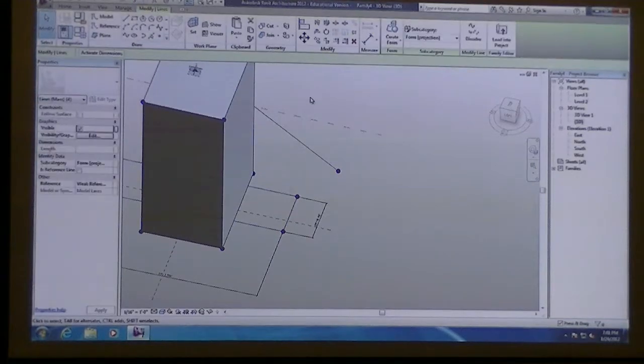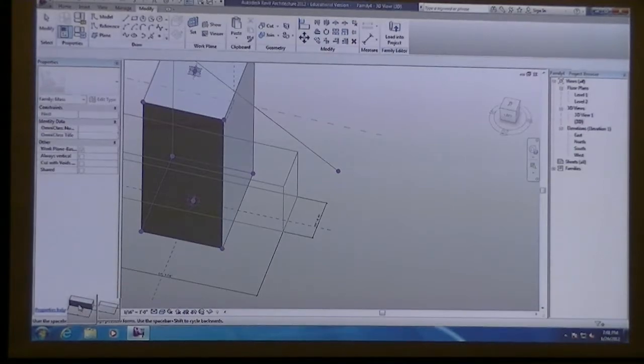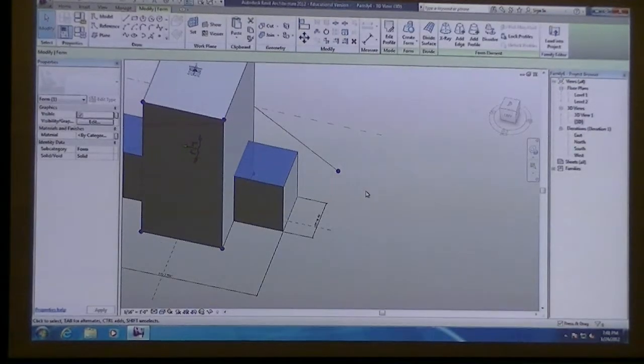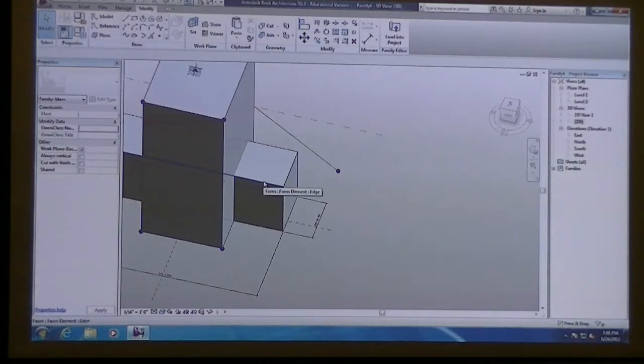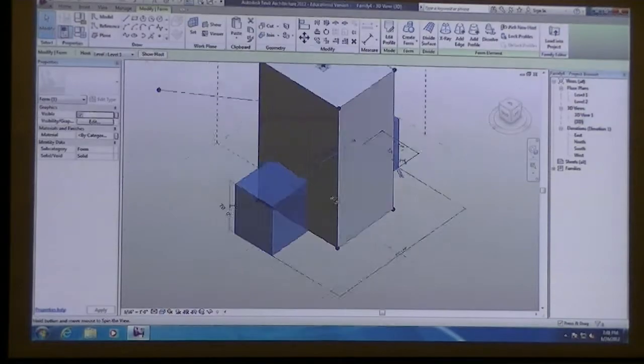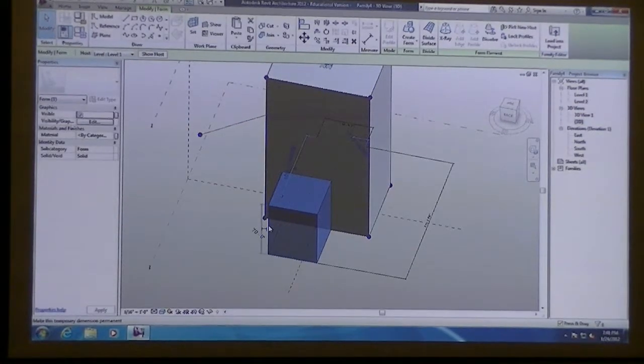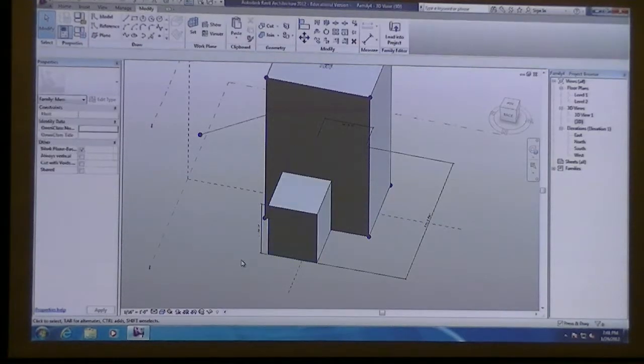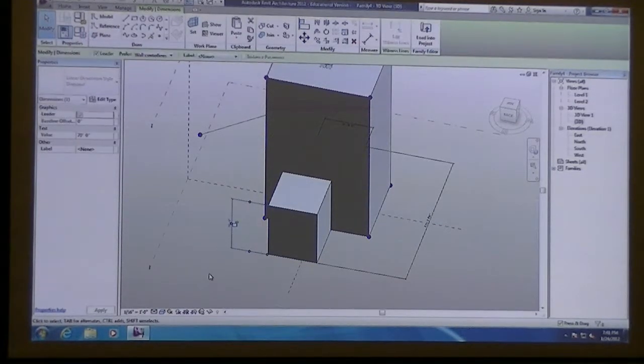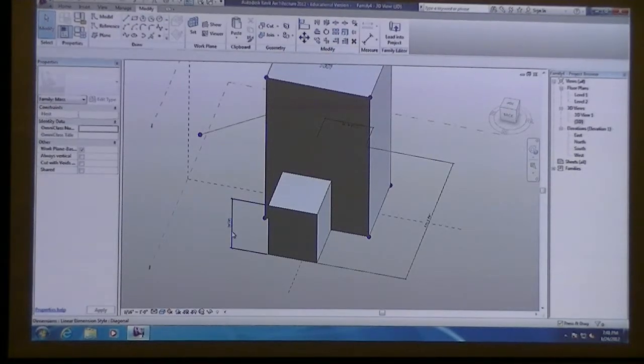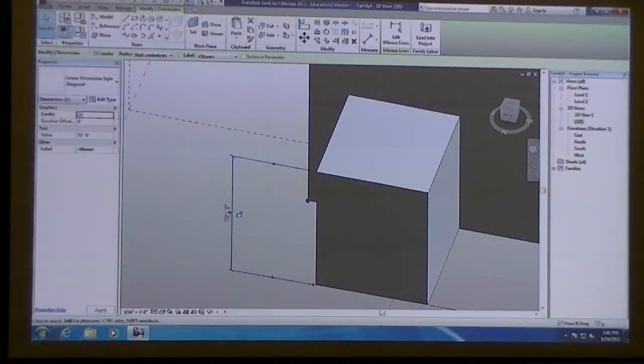And then when we create the extrusion, create form, and pick our solid, if you hover over or tab over that form element so that you can select the whole thing, on one of the temporary dimensions you should have a height associated with it that we could click on that dimension string and make it into an actual permanent dimension that we could also assign a parameter to.